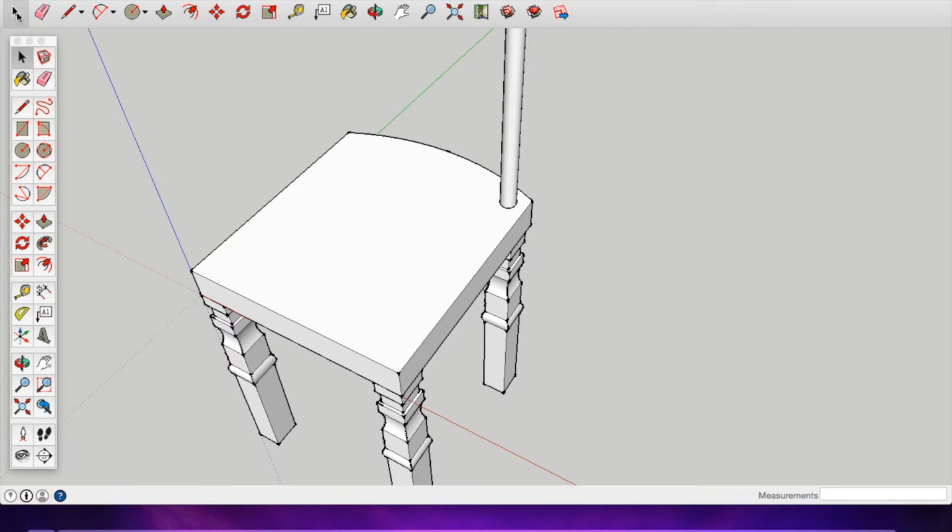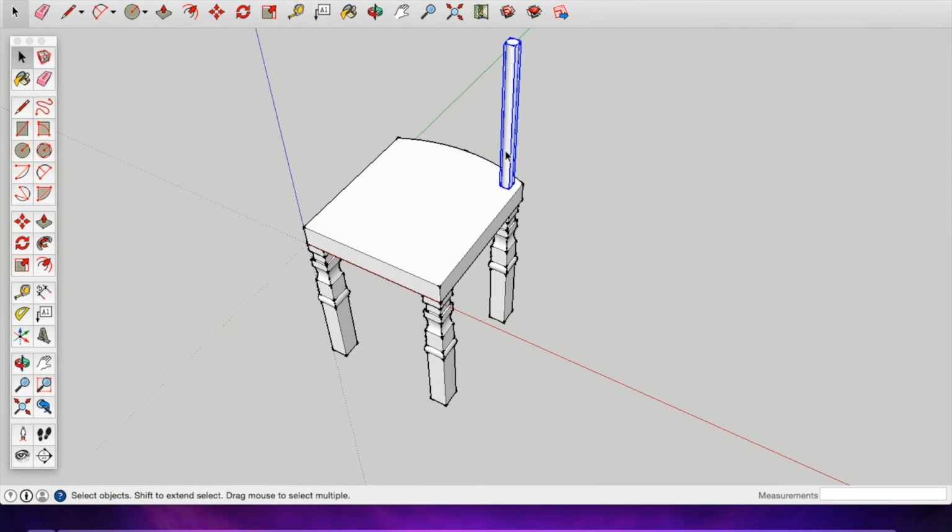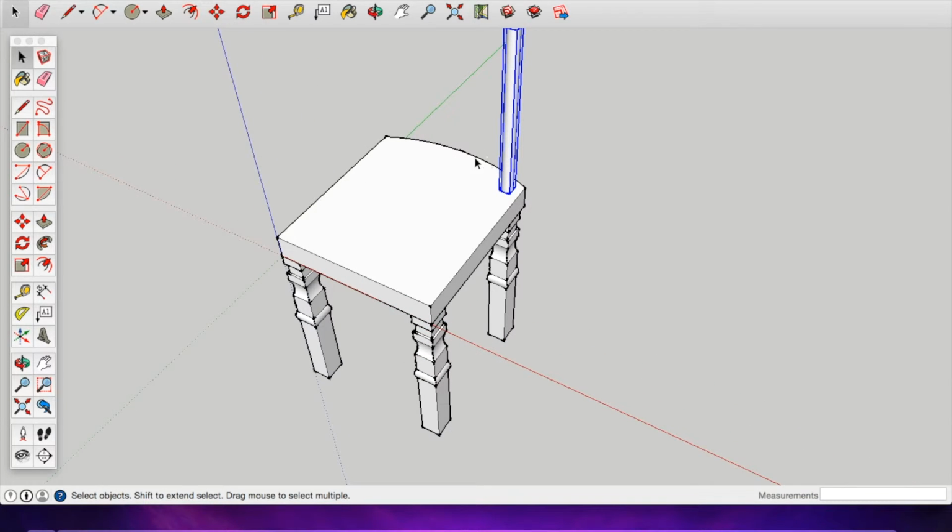So I'm going to click on the Select tool. I'm going to click on the component we just made, that chair back cylinder. Then I'm going to choose this button. It's the Rotate button. Okay, it's 2 arrows pointing in a circle at each other. And it's really important here that you see how my tool here is blue. You want it to be blue. If I end up going on this side, it turns to red. Okay, and then I could go on another side, it turns black or green. We really want it to be blue for this particular thing we're doing.